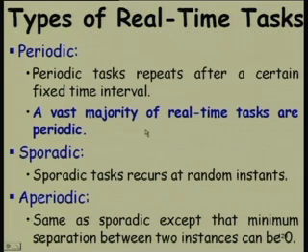We had also seen that the tasks are periodic, sporadic or aperiodic. There are three main types of tasks that we will be talking of. Periodic occurs after a time interval, somehow some clock is set, gives an interrupt, and most of these periodic events are polling in nature, and we will see that a majority of the tasks that will be concerned are actually periodic tasks.